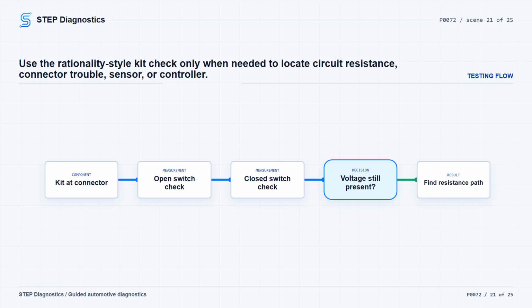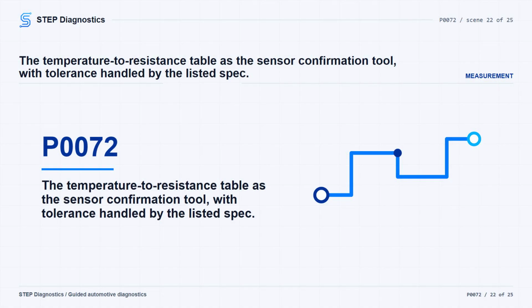find which circuit has resistance by moving the test lead from the sensor ground circuit to a good chassis ground. Then isolate the suspect circuit and measure resistance between the sensor and ECU harness connectors. If no resistance is measured, check the connectors in that path for spread, dirty, or corroded terminals. If the circuits check good, move on to verifying whether the issue is with the temperature sensor or the ECU. When the path points toward the ambient air temperature sensor, verify it with the temperature and resistance information when you can. The actual resistance can vary +/-10% from the values in the table.